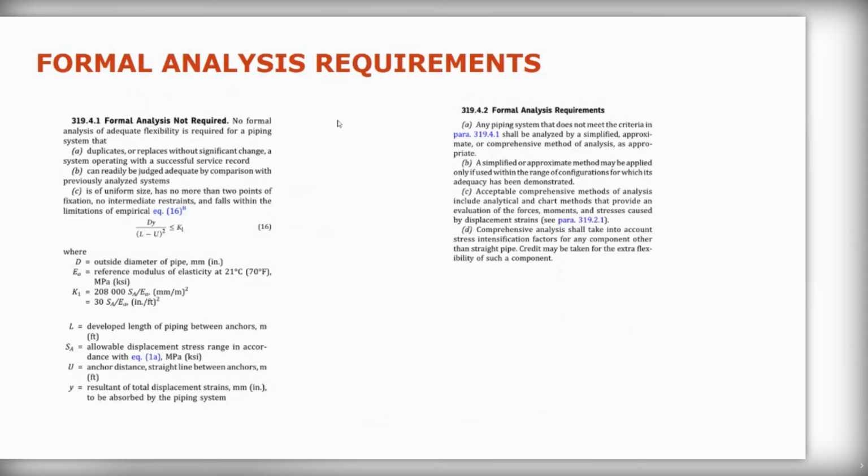That's all good, but then the question is, how do you work out all those stresses? In some cases, you can do it easily using, as we said, just basic equations treated as beams. For secondary loads, that would be very hard to do. And we'll talk a little bit about simple ways of doing it, but there are not many and you quickly run out. That's where you push towards using formal pipe stress analysis.